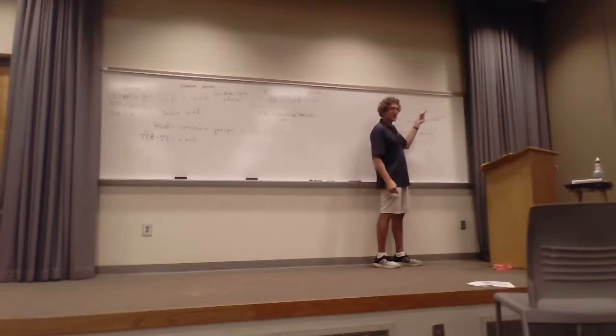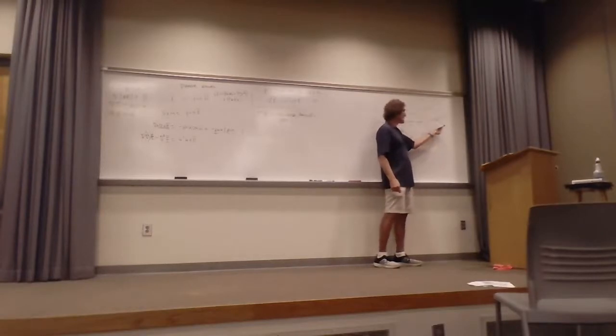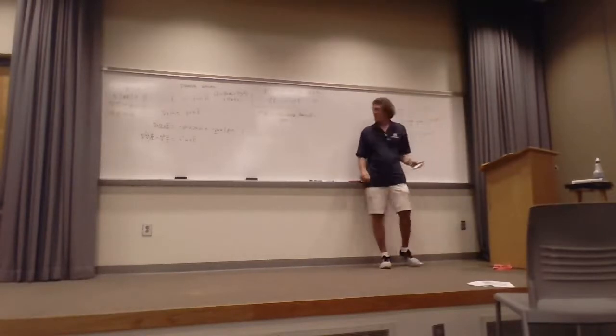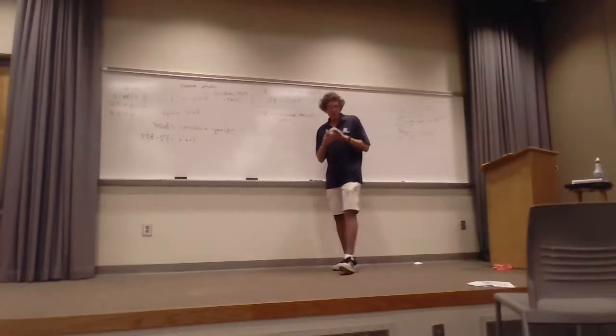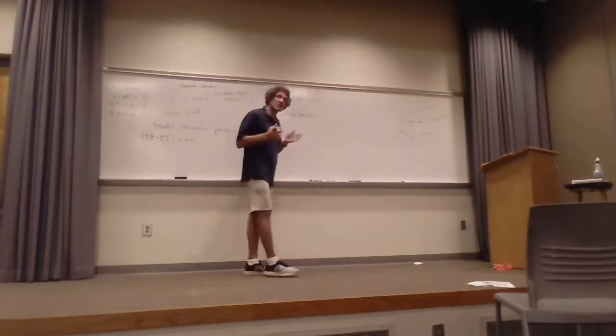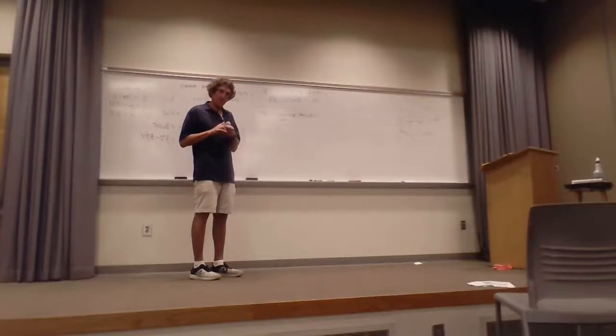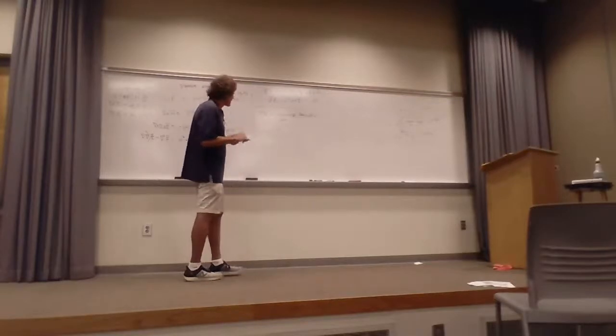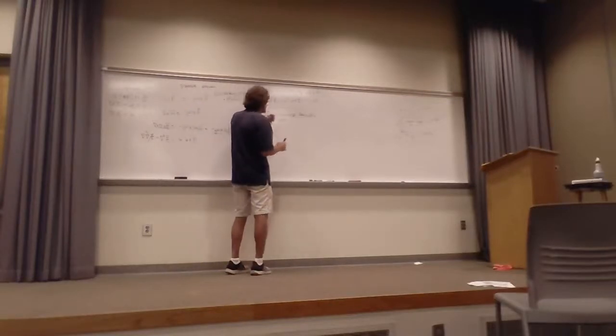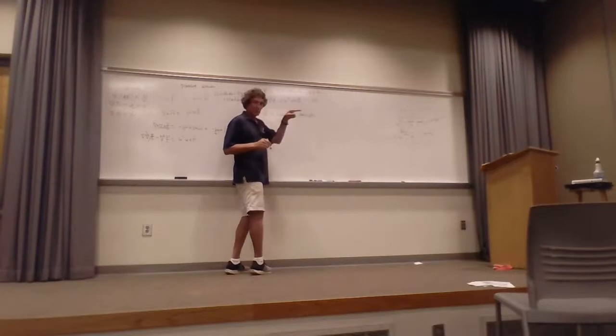So transverse magnetic means the magnetic field is perpendicular and in the direction of propagation, or down that z-axis is 0, because it's slamming into the lower and upper boundaries. So this is a TM field with respect to the boundaries. Do you follow me on that? The conducting boundaries. That means it only has an EZ field in the direction Z.